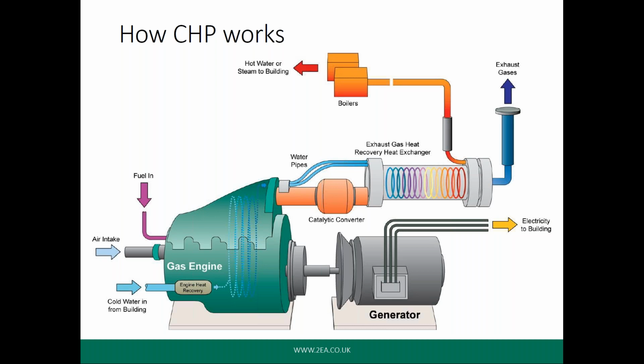It is not essential to know the innermost workings of a combined heat and power unit. It can be treated like a black box, but as an engineer, I always like to try and gain at least a rudimentary handle on any technology I work with. So here we have a stylized representation of the main components of a combined heat and power unit. Starting on the left-hand side, you can see the prime mover, typically a diesel engine converted to run on gas, most of the time natural gas. This drives the generator to produce the electricity for the site.